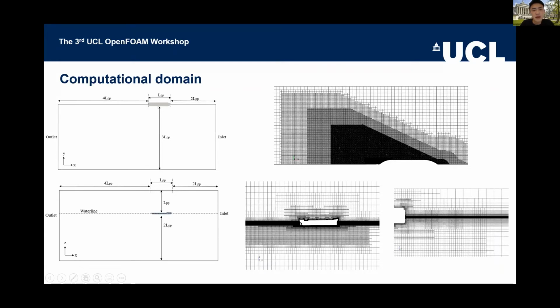This makes the sea behave like an open sea. It's like an infinitely big sea in real life, but modeled in this way. These numbers come from my experience, so they should be safe values, with the computational domain sufficiently large to be considered as infinite.